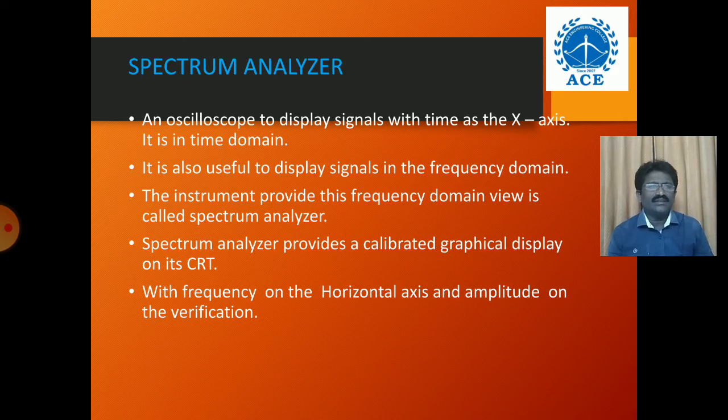That's the reason we have to carry out a maintenance process. With the help of a power analyzer, you can measure such variations in the power supply. Actually, this has some sensing elements connected to a multiplexer. The output of the mux is given to an analog to digital converter.